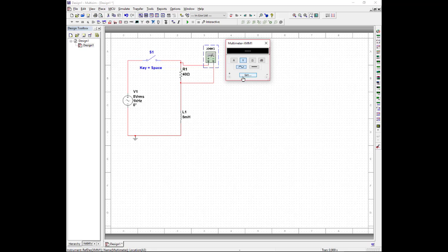We can also measure current. Again, it's where you connect up your probes for the current. Make sure when you're connecting up your current probes that it goes in line, in series with the circuit, whereas your voltmeter obviously is in parallel, as we've done there. The other thing we're going to do for this one is connect up an oscilloscope.